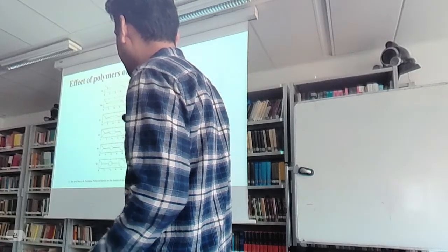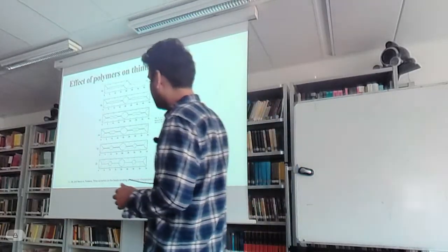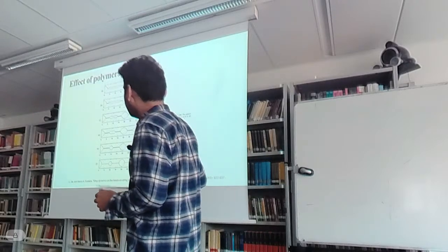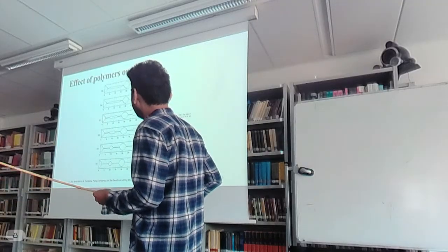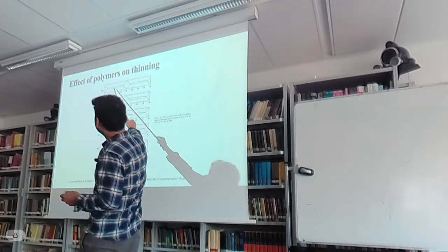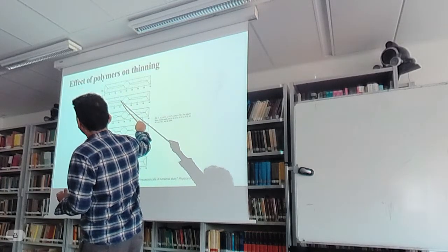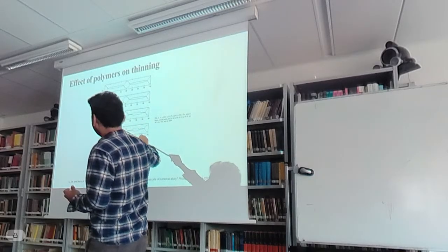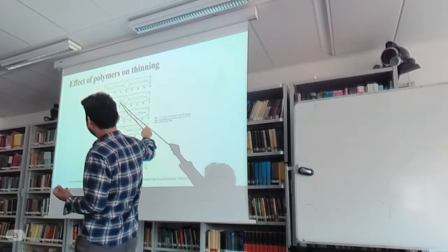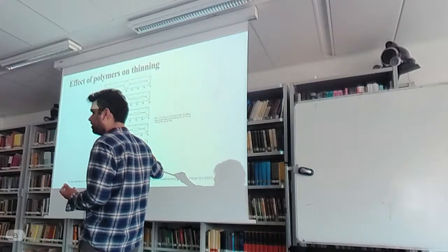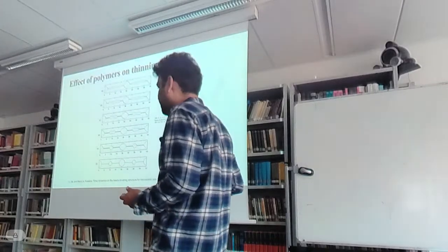But then I think this is because of this problem that we have here, that we are in a large Weber number regime. So these are some simulations from Fentelos and J for the large Deborah number but finite Weber number. There also they found that they go to some bridge thickness, but then surface tension kicks in, and this bridge becomes unstable and you make a bead on a string structure where this bridge collapses into smaller droplets, and then there's a cascading effect that this will happen to this bridge until it breaks.